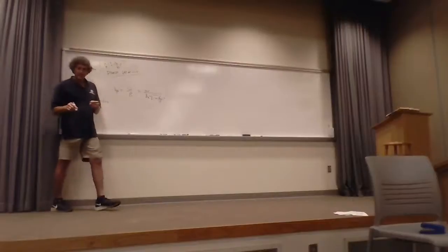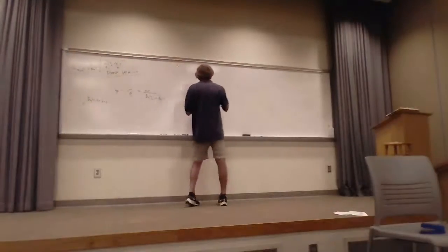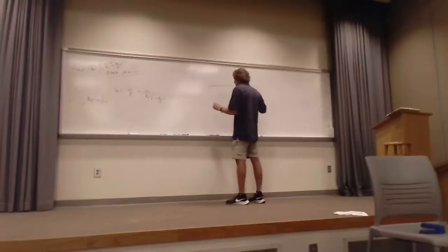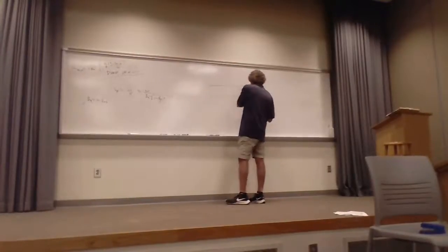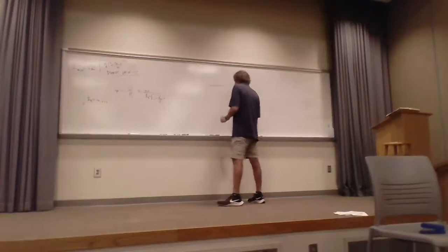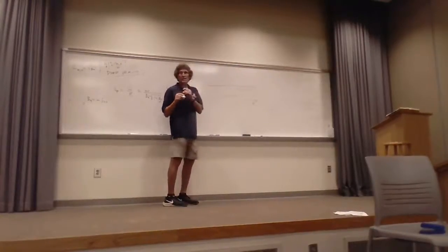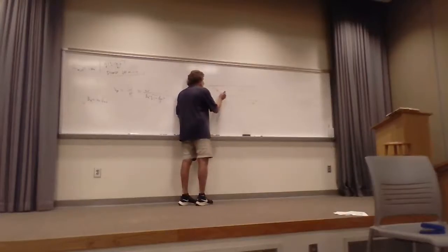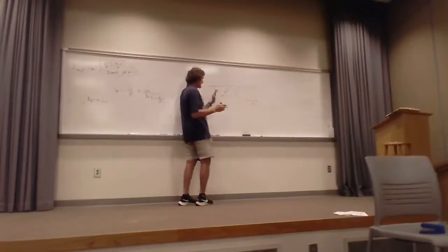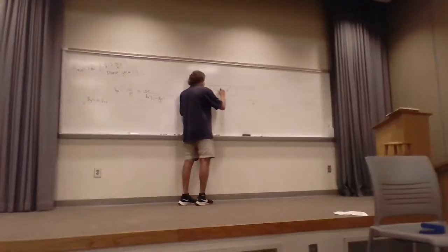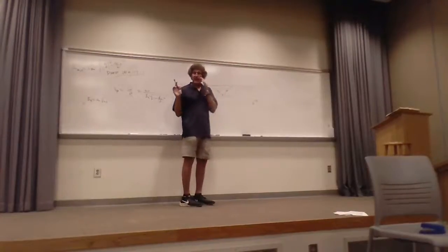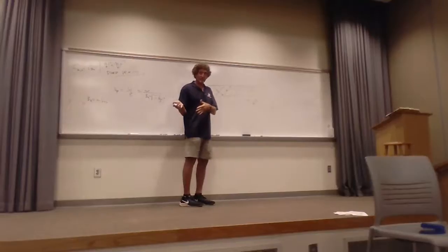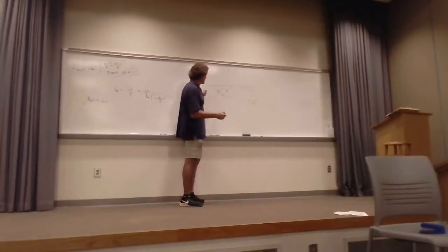What does that actually mean? Let me try to explain this. If I look down the guide and split it in half, looking right down the center of the guide, this is the z-axis here. One way of explaining phenomena in a guide is a superposition of two wavefronts. If you have a wavefront progressing this way, reflecting, and then going like this, you can actually take one that way and then one the opposite way. And in fact, that will be a solution of the differential equations. Right? It works. But they're propagating at a given angle.